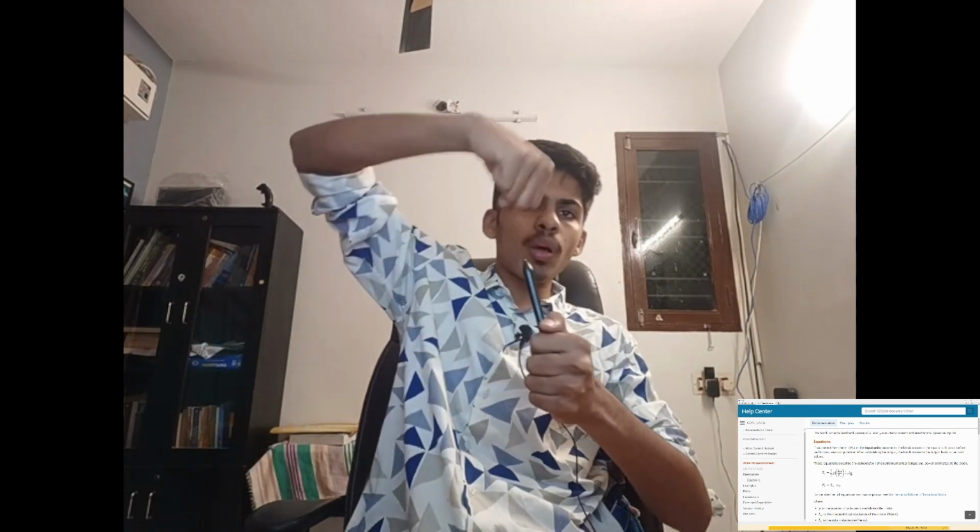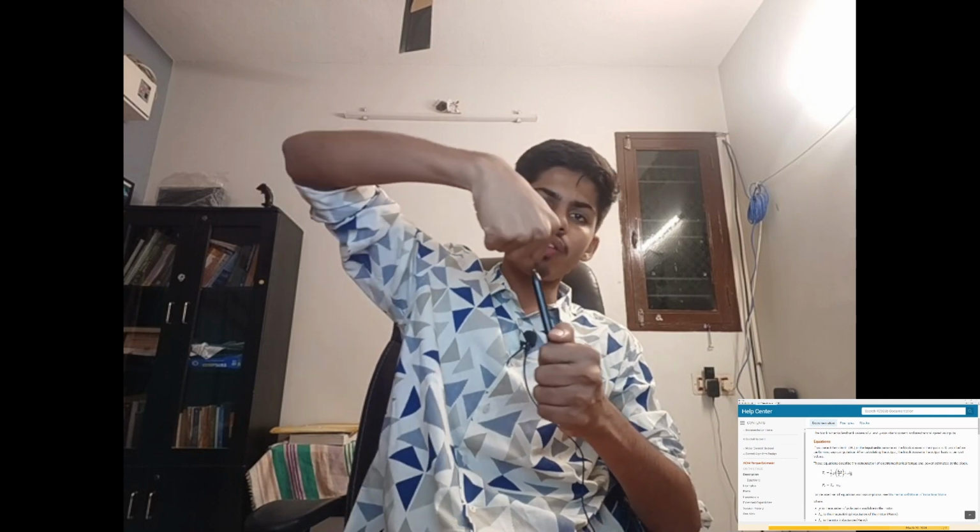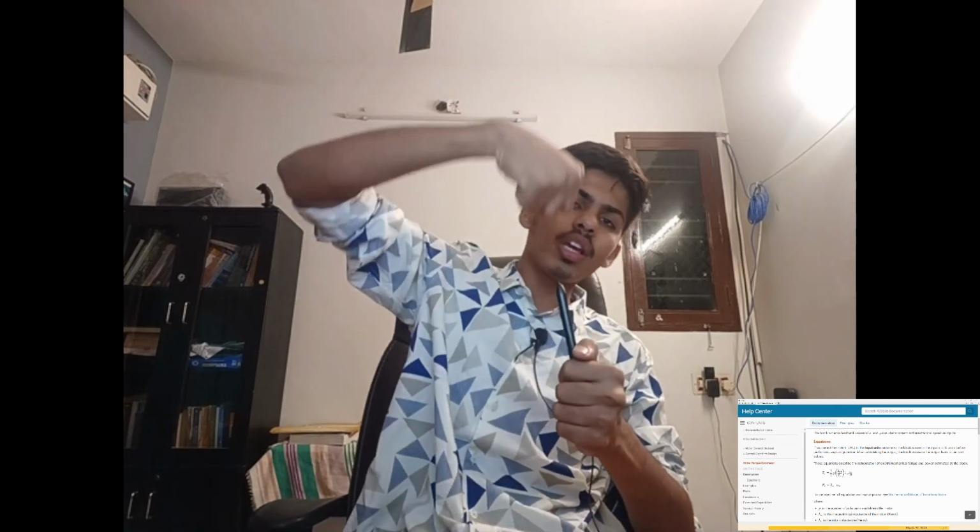So if you pull the motor from this direction, so this is the stator, this hand is the stator. So if you pull the rotor like this, you will not be getting any torque. The rotor has to spin like this. So you have to get the much torque from the quadrature axis. So how much current you have to maximize? So that is the aim of the FOC. You can maximize the quadrature axis component to maximize the torque.